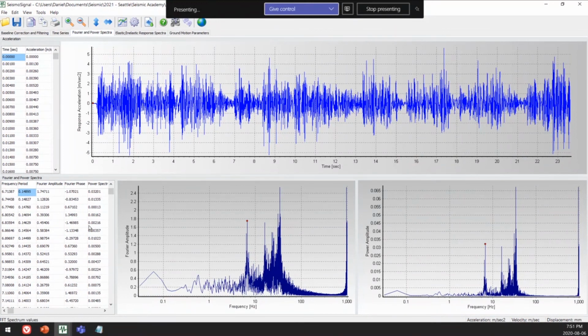So it's going to pick up on higher mode shapes as well, which is one thing to note, because the tower is made up of obviously a bunch of different modes. It'll also pick up on the fundamental frequency of the shake table itself, because the shake table also vibrates at a certain frequency. So be mindful of that. But what you want to know is the largest first peak, because the fundamental frequency is going to be as low as possible.